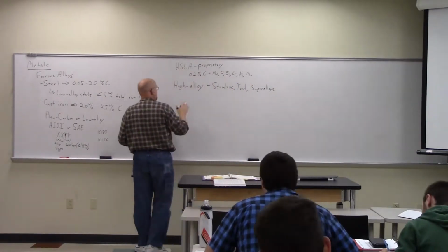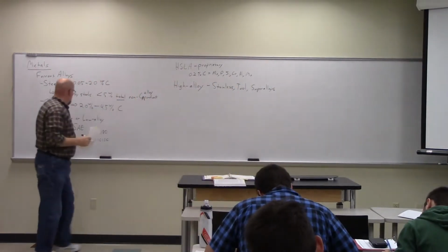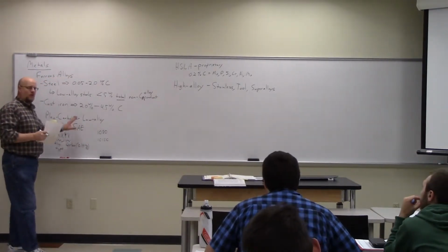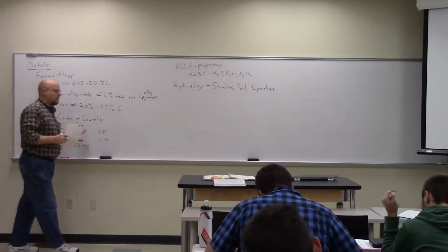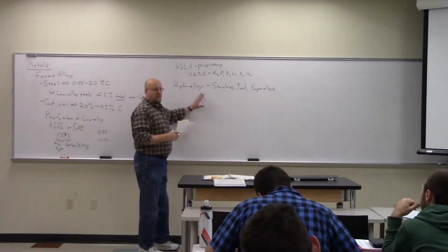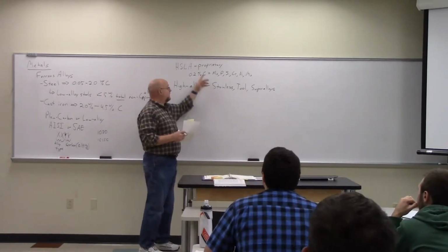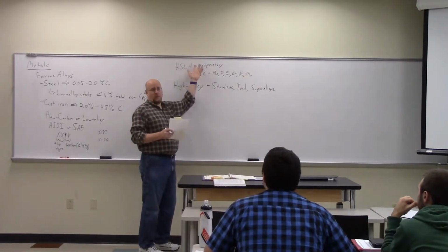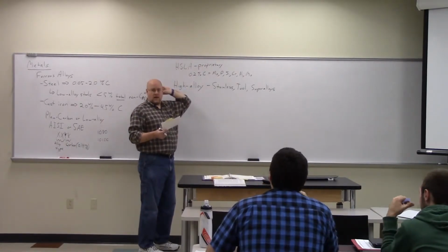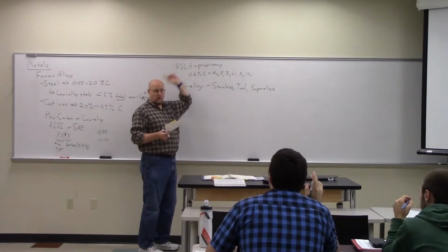So, this is the common, right? The plain carbon and low alloy steels over here are fairly common use. The stainless steels also fairly common use, so we have actual structure for doing things. We can't do HSLA steels because they're proprietary. They don't have an AISI or SAE kind of designation because they're proprietary.